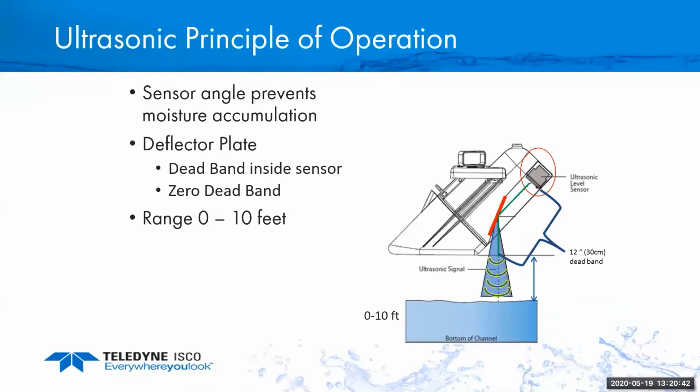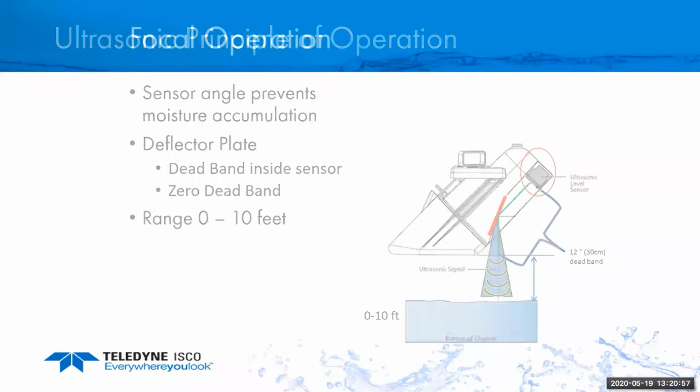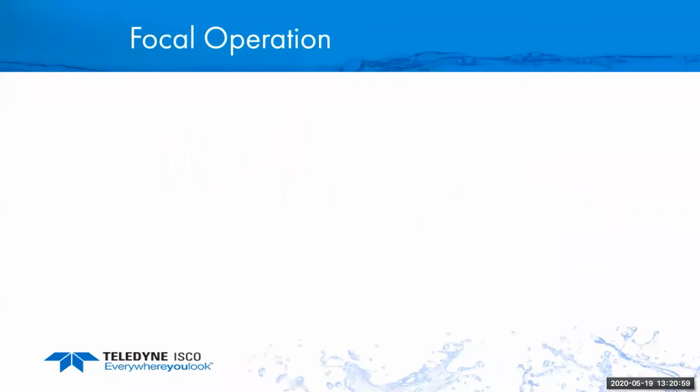You see these a lot in stormwater applications, CSOs, big pipes and things like that, where when you do have rain, the world's coming to an end kind of thing, and it can just tear the sensor out. So you want something that's not in the flow, and this technology works well for that.